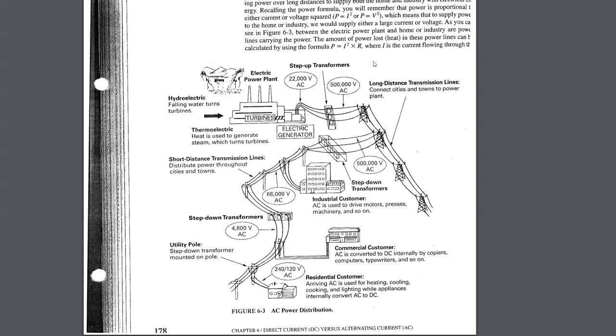I squared R is, of course, power. So I squared R in a wire is usually considered a loss. I squared R losses are reduced if I drop the current down, and that's what happens when I use the step-up transformer. So we step the voltage up, we transmit the energy, high voltage, low current, out over these long distance transmission lines, and again the voltage is 500,000 volts.